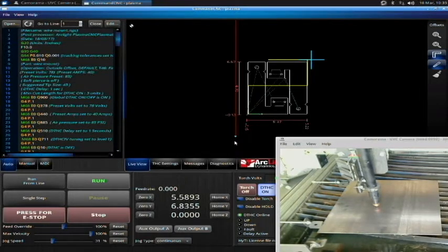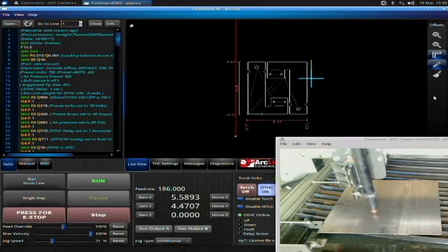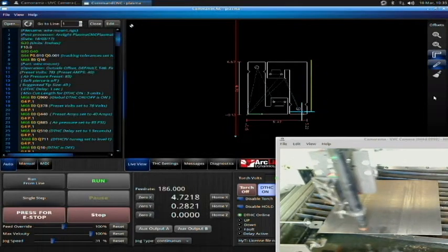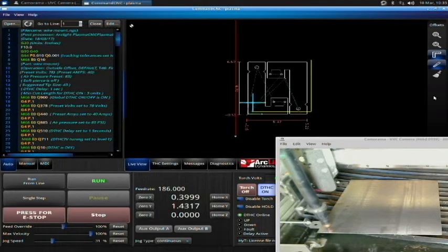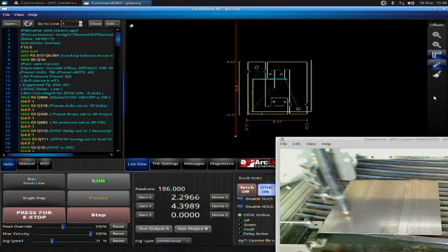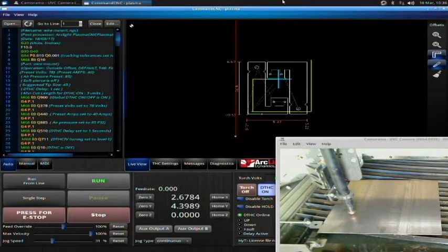So, and again, if I want to get rid of this yellow line, I can simply click that button. So my part 0 is set, so the machine knows to start the cut down at this lower left. Okay? So I don't have to actually jog back to the 0 point once I've set my machine 0. If I hit run, the machine will go to the first cut.